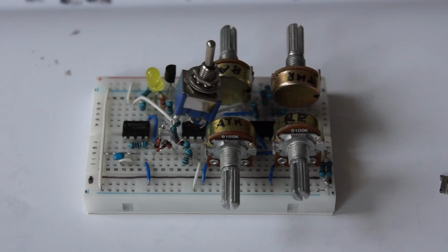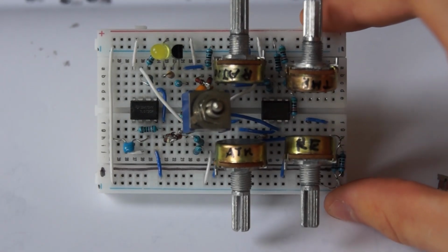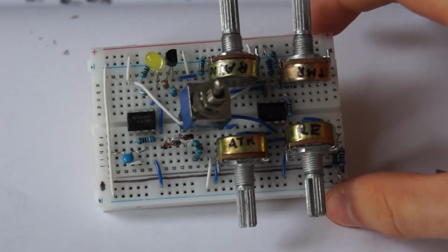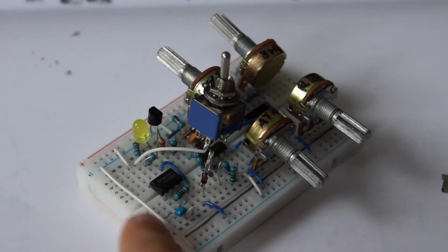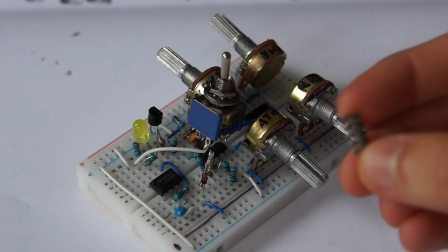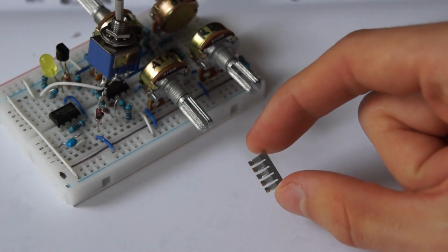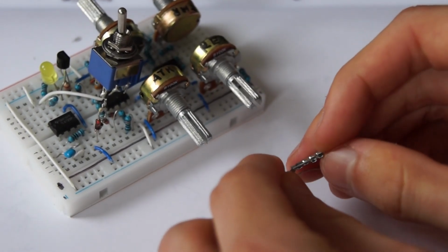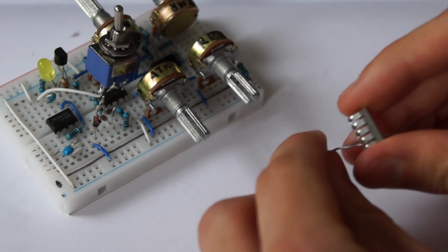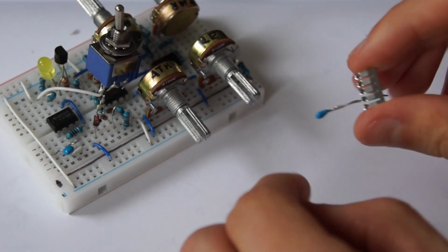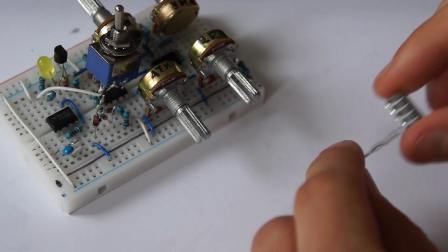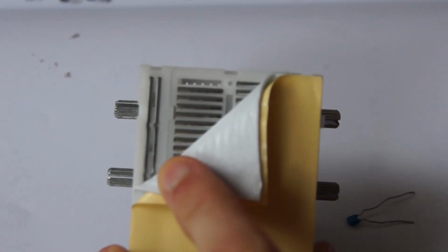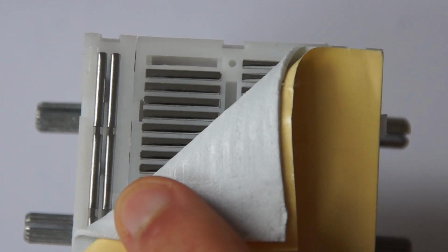This is a breadboard. This one is filled with components. The way that these work is that there's these long horizontal lines that you can easily connect to power, and then there's small vertical lines, and they just connect together using these little connector pins. These things are useful because it's very easy to put components into these pins when there's plastic supporting them, and you can very easily take them out and they will make contact. If I pull off this sticker, you can see how all the connectors in the breadboard are aligned.